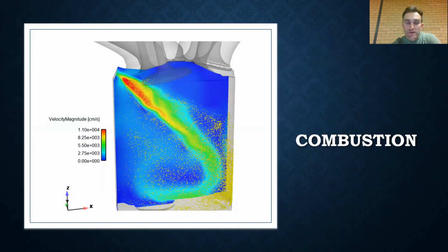The third solver is combustion. This uses the ANSYS Forte solver to simulate the complete combustion process of the engine and allows for the analysis of the entire combustion event and the tracking of the flame front after combustion occurs. I'm yet to perform a combustion simulation, but given that the port flow takes around 25 hours to solve and the cold flow takes around 50 hours to solve using the default settings, I'd imagine that the combustion sim would be a pretty lengthy simulation given the complexity of it.